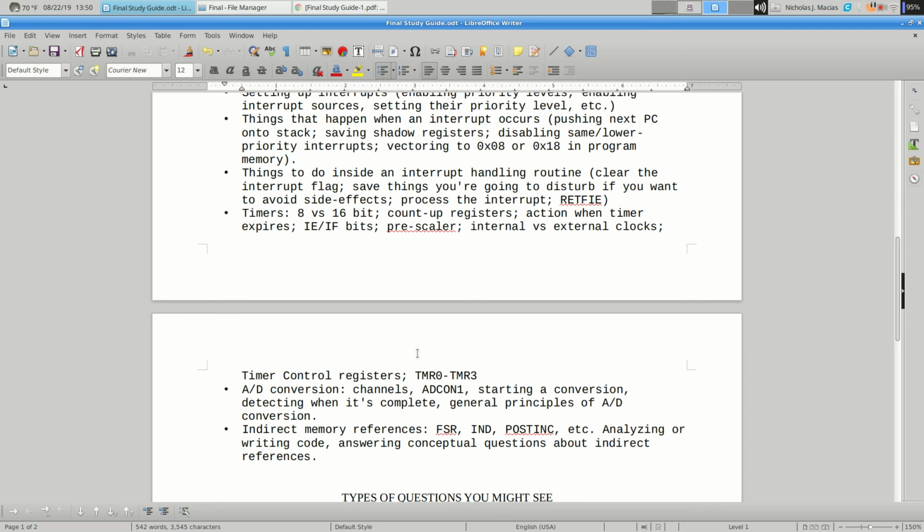System clock is 32,000 divided by 4, you get 8,000. That's how many instructions happen a second. So an instruction is an 8,000th of a second. If you don't set any funny prescalers or anything, basically every instruction your timer 0 register increments. And when it overflows, it requests an interrupt. That's the whole timer subsystem.